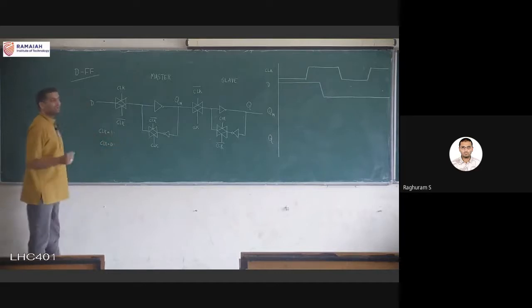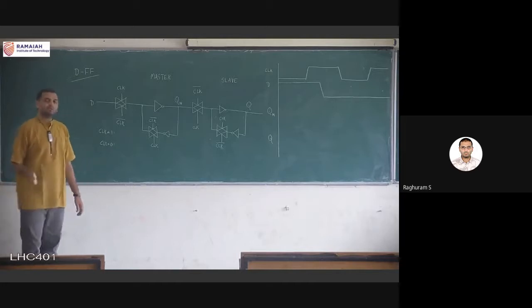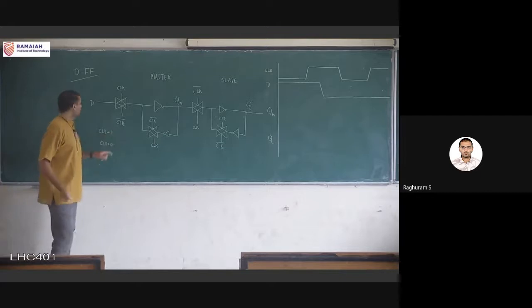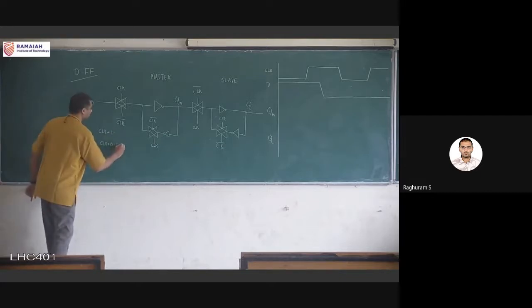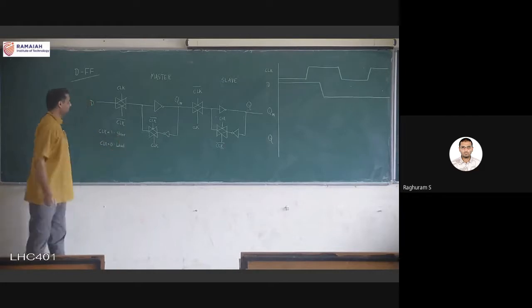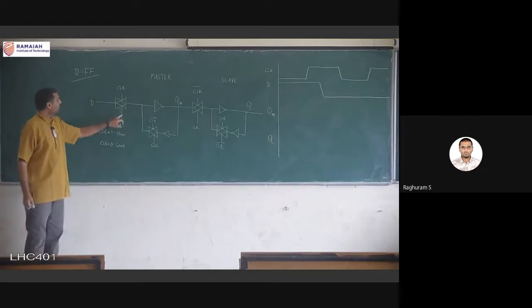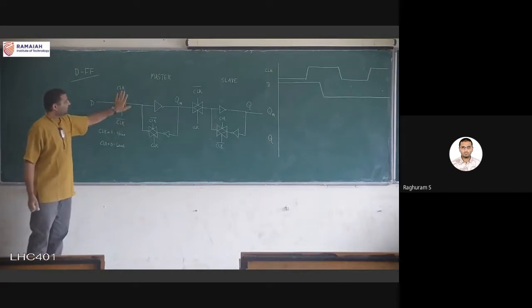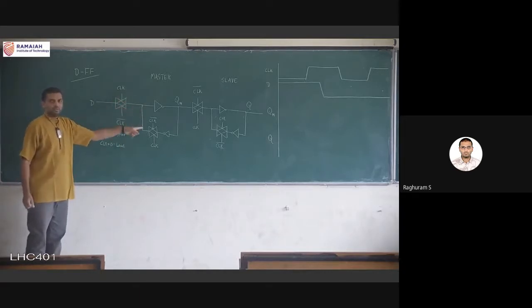which is load and which is store. When will this particular latch load new data? When clock equal to 0, right? Because when clock equal to 0, it will take the new data. When clock equal to 1, it will not see this, it will be storing the old data. So that much we know.